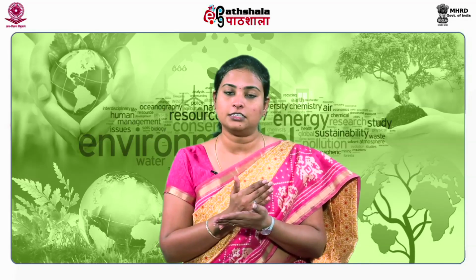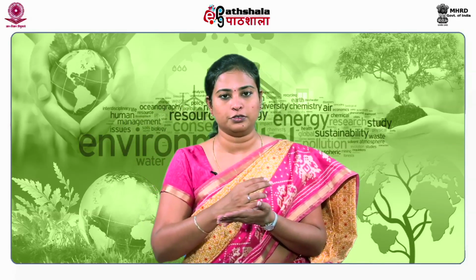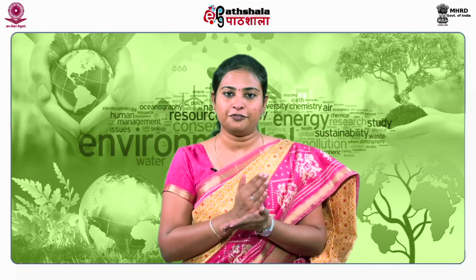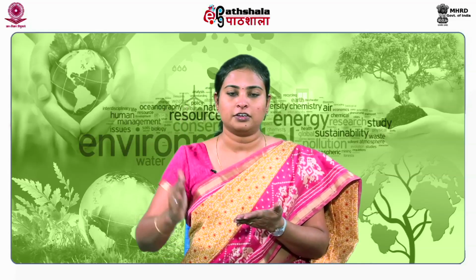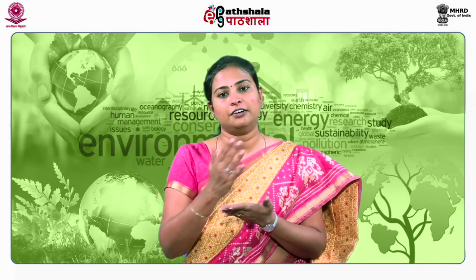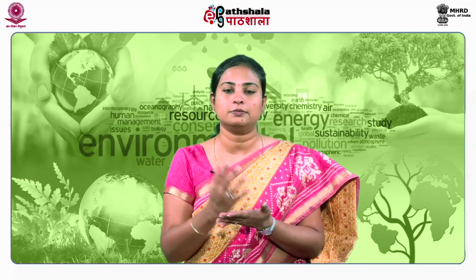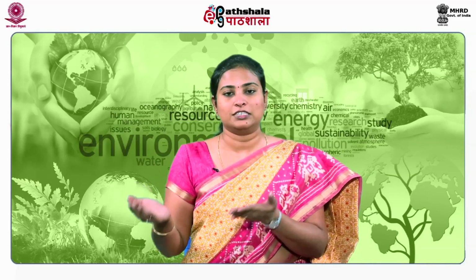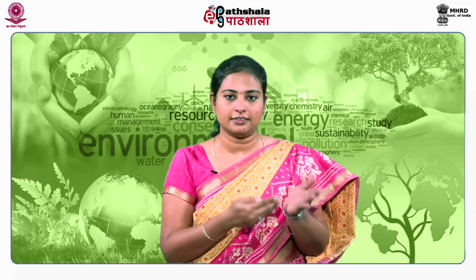In the fill condition, you fill the wastewater into the unit where you have a mass of microorganisms in the reactor. Once the fill is done, you aerate the mixture and allow contact of the microorganisms with the liquid. Then comes the settling period, which is similar to a secondary clarifier or secondary sedimentation tank.